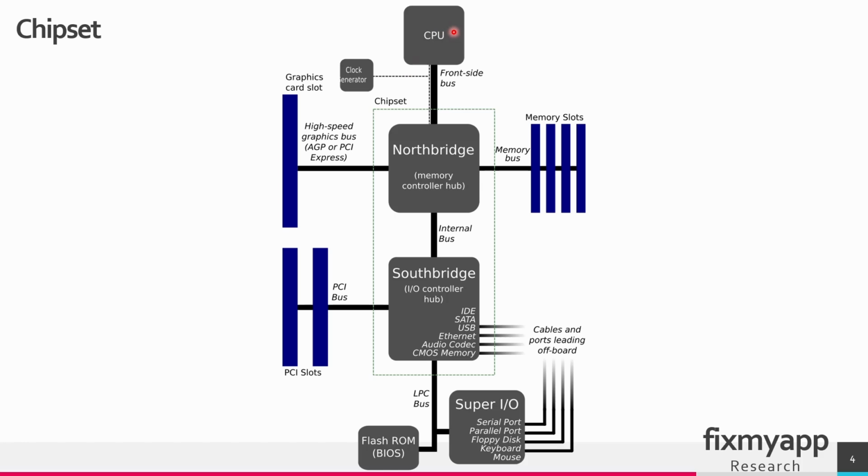As CPU technology grew, processors started to integrate more capabilities directly on the CPU die. For instance, Intel and AMD began embedding the memory controller and the PCIe controller directly into the CPU itself. This reduced the need for a separate North Bridge chip, as the CPU could now handle high-speed data tasks internally, improving the performance and reducing the latency between the CPU and these components.